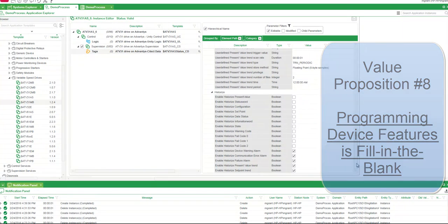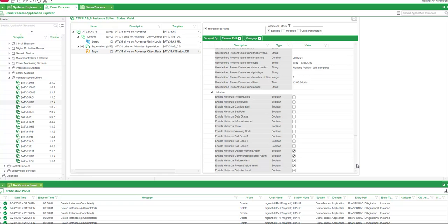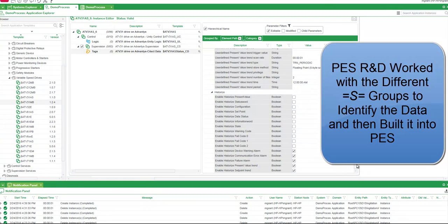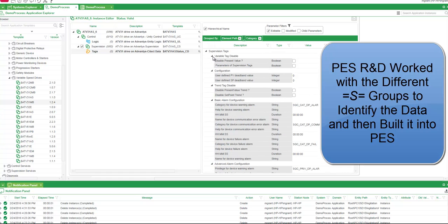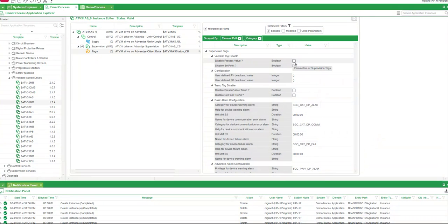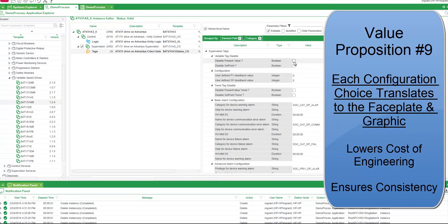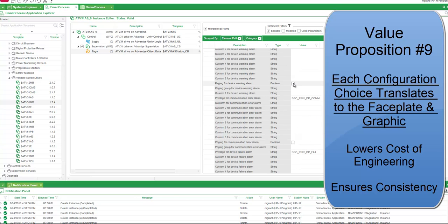So what we said, we meaning the Modicon group, said, okay, if this is the information coming from the ATV group, let's put these attributes into this object, and let's let the engineer building this control application, in this case adding a variable speed drive to that agitator motor, really easily, with clicks of a button, go through and configure how this variable speed drive is going to be configured. And that's all we do.